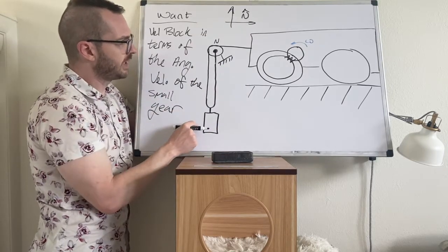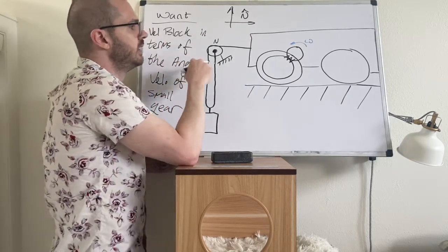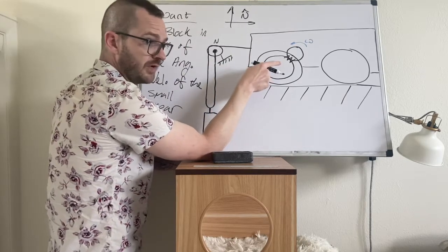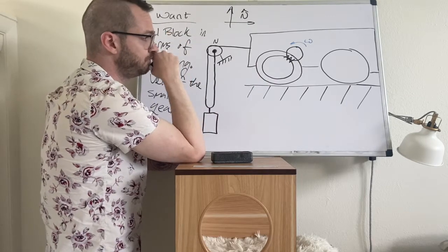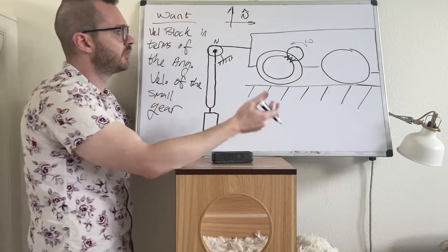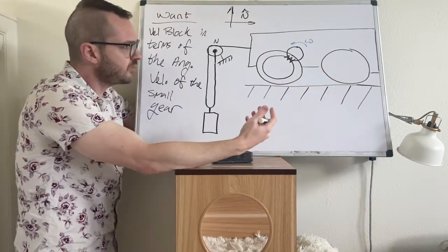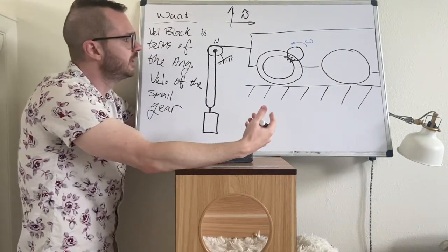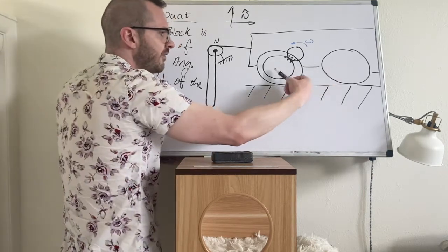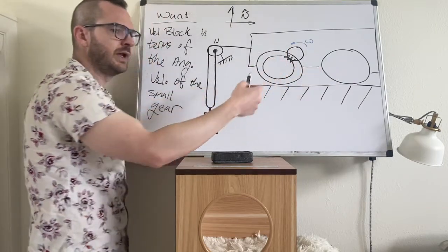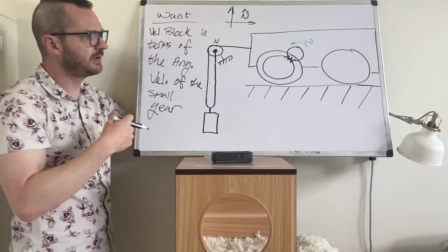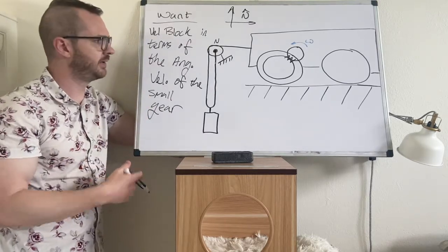So we've definitely got one body here. We've got the cart, and we've got the wheels attached to the cart, and we've got the little gear. So we could make the cart a body, and make the front wheel a body, and make the rear wheel a body. If we wanted to generate the full dynamics, that is what we would need to do, because consider the wheels have mass and inertia. The cart itself is going to have some kind of mass. For what we're doing, analyzing this, we're still in the kinematics part of our study.